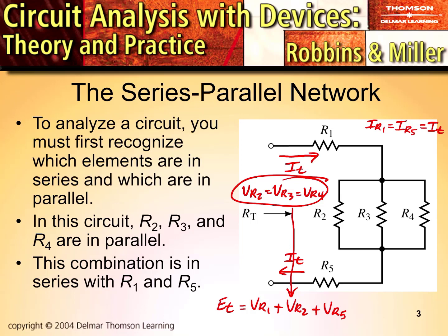It means a few things. If we have voltage and resistance of R1, we can determine current. As a result, that means we're going to have this current as well. If we can calculate the voltage here, having the voltage and the resistance to give us current, we can use the current that we just calculated to determine the voltage of VR5 and so on.